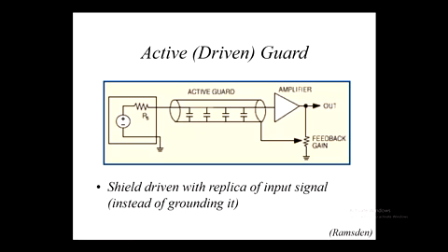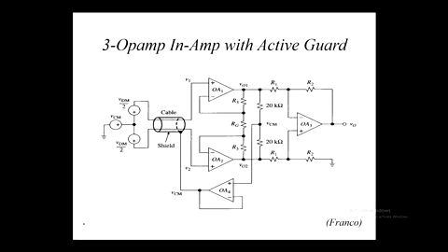It turns out that even though this diagram, the previous diagram, is not very detailed, a bit notional, it highlights the fact that it's invariably useful to reduce the amount of signal that goes back, not exactly as shown here, a complete value of VCM being pushed back on the shield, but a fraction of VCM, maybe a large fraction, but not the complete amount. And the reason for that is that we can get instability occurring with these systems.